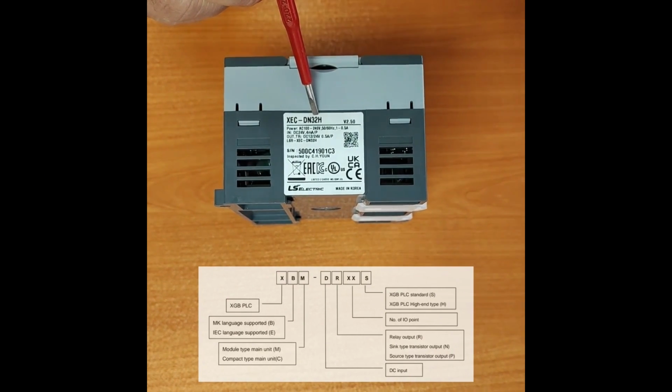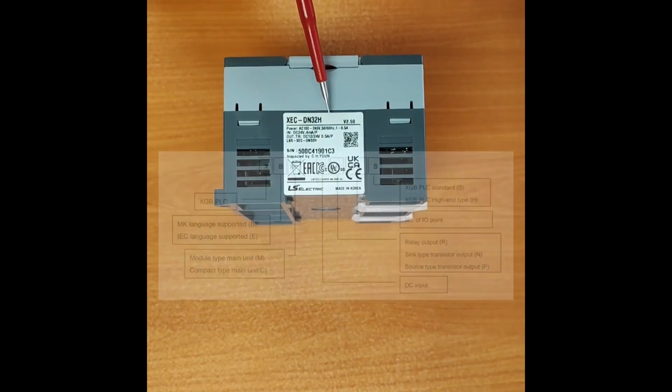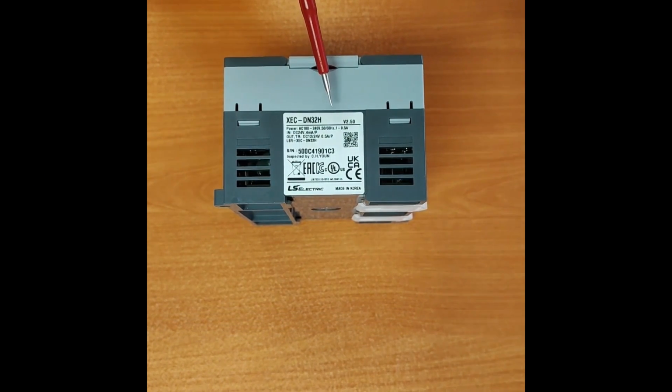And now the last letter, which indicates the PLC series, here is H, meaning we are going to review the H series PLCs. Some PLCs after the letter H also have a slash and then D1. What is meant by /D1 is that the PLC itself operates on 24 volts DC, and if there is no /D1, like this PLC you see here, the PLC itself operates on 220 volts AC.